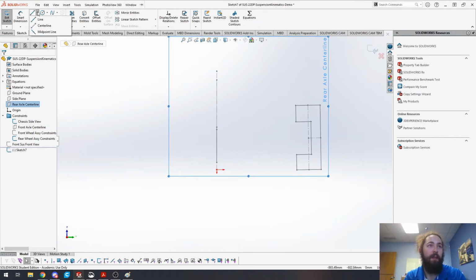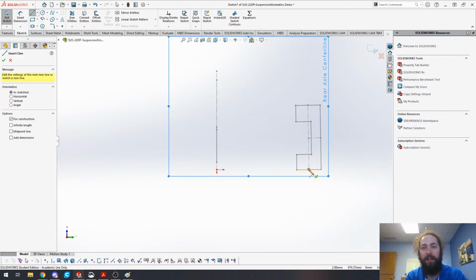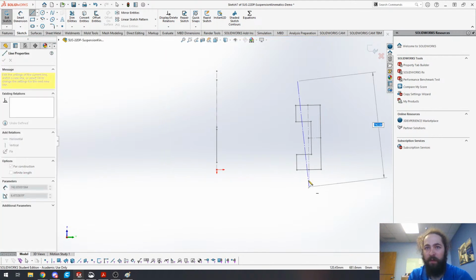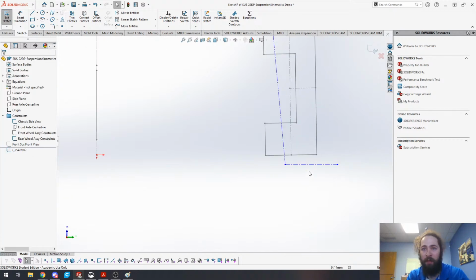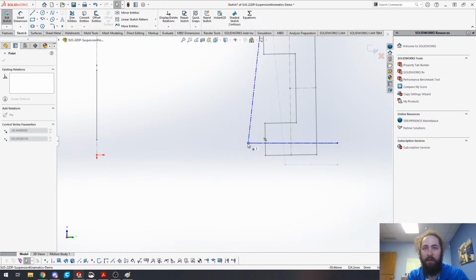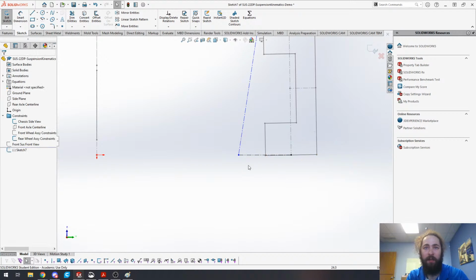And then in this case, our scrub radius doesn't really affect things. This is a point where you can make a decision where you can say, hey, am I going to have front and rear uprights be identical, offsets be identical, all that kind of stuff. And that's where you start to place this theoretical axis where your points are going to be located. So in this case, yeah, we are using the same design of upright front and rear. We're making that coincident there.